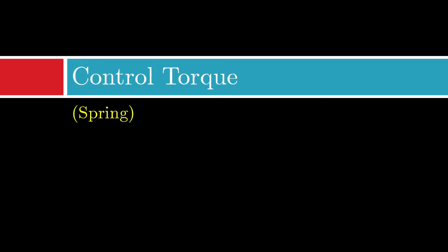I also suggest students to see the aluminum disc, which also has dots on its surface. So you need to think why such dots are provided there on the aluminum disc. Since the shape of the disc is not perfectly circular, hence you can also find a balance weight kept on the disc surface. This suitable balance weight is provided on the part of the disc which has a smaller area.